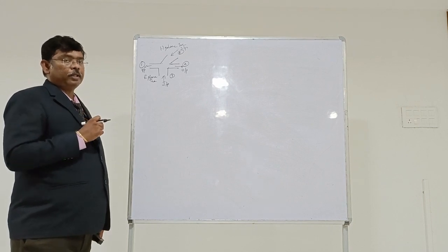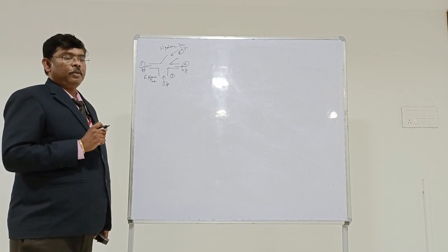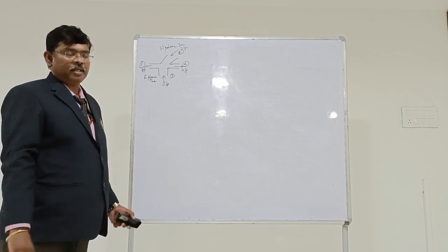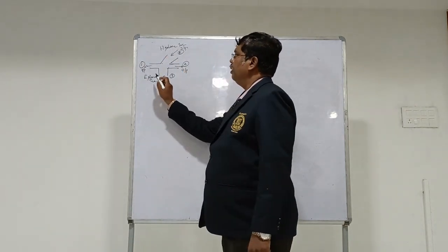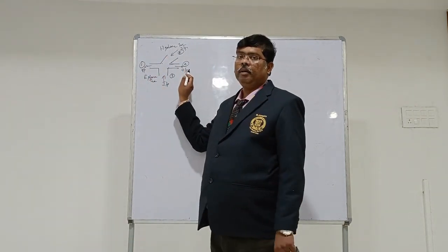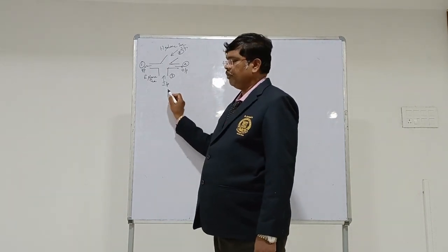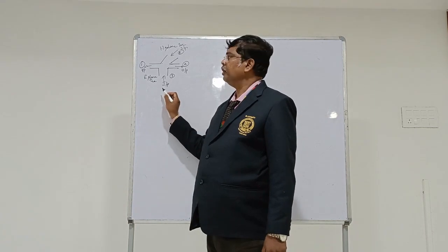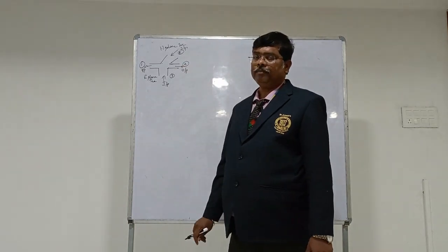It's a 4-port network. For that, first we have to write the condition, and using the symmetry property we have to extend the condition. Hope you can understand. That is, the 4 ports are available. Port 1 and 2 will be the output ports. Port 3 is for the E plane T input. Port 4 is for the H plane T input.